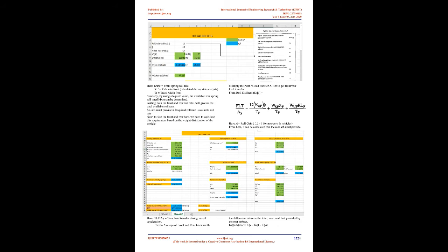Rolling moment lever arm equals sprung mass cog height minus the front roll center height plus the rear roll center height, with the front roll center height weighted by the sprung mass weight distribution. Rolling moment per g lateral acceleration equals HRM, where HRM equals the rolling moment lever arm calculated above. Now, dividing this value by the desired roll gradient will give us the roll rate required, KF. Roll gradient should be taken between 1.5-3 deg/g for an FS vehicle.